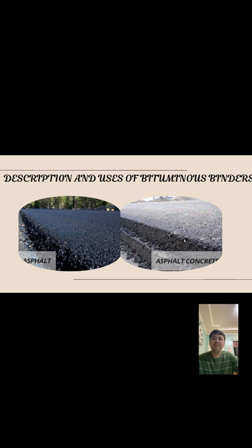The asphalt cement grading by penetration and viscosity. Historically, asphalt cement grades were determined by penetration, which measures the depth, in 0.1 millimeter, that a standard needle can penetrate the material under specified conditions of load, time, and temperature. Soft asphalt cements have penetration values between 200 and 300, while harder grades fall between 60 and 70.